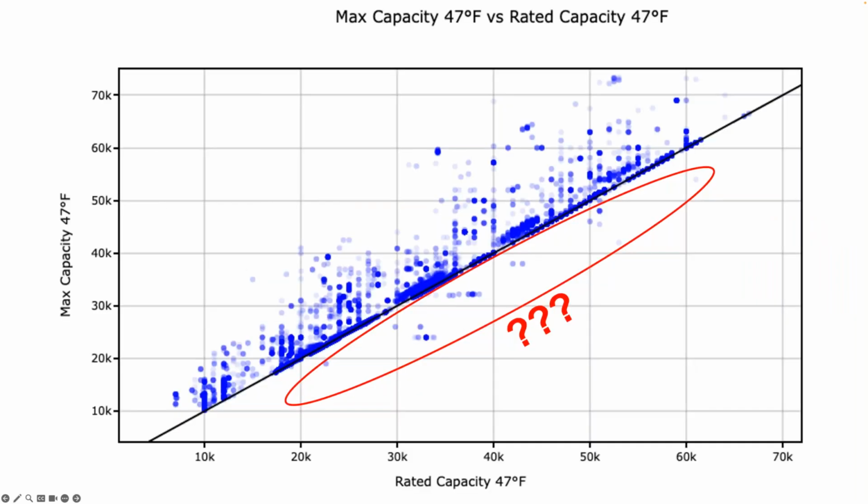However, on closer inspection, some of the data is obviously problematic. Like in this example, we have a rated capacity that is higher than the maximum capacity, and you'd see the same thing where you'd have minimum capacities that were higher than maximum capacities. There's some cases where the COPs were greater than Carnot efficiency, which is physically impossible. And I think a lot of the data in here is not necessarily, you know, the manufacturers trying to make their equipment look better than it is. I think there's just a lot of data entry issues.